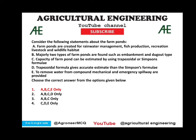Consider the following statements about the farm ponds. Farm ponds are created for rainwater management, fish production, recreation, livestock and wildlife habitat. It is correct. Majorly two types of farm ponds are found, embankment and dugout type. It is also correct. The capacity of a farm pond can be estimated by using trapezoidal or Simpson's formulae. This statement is also correct.